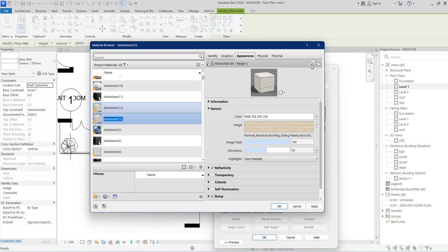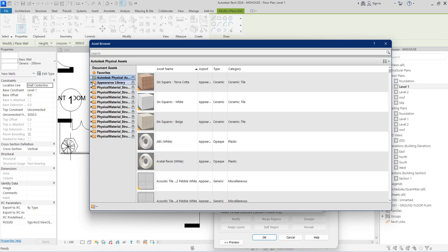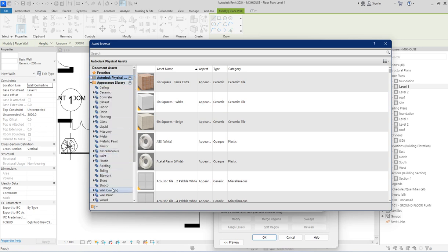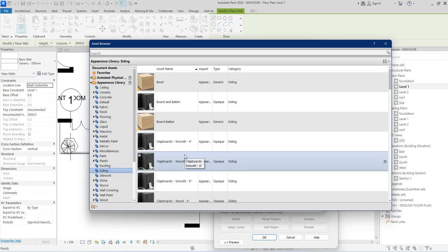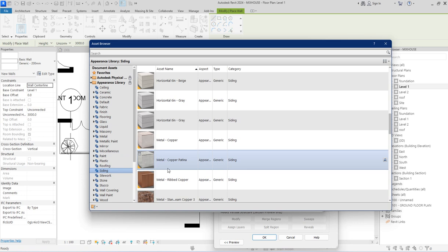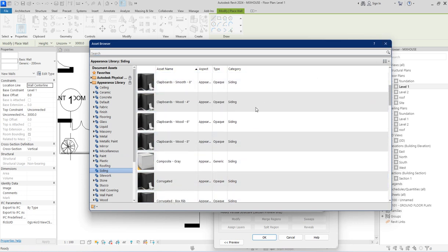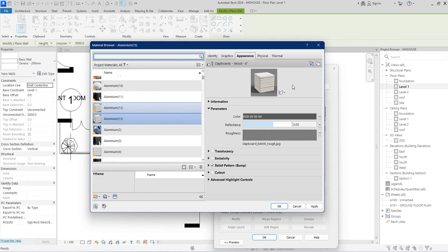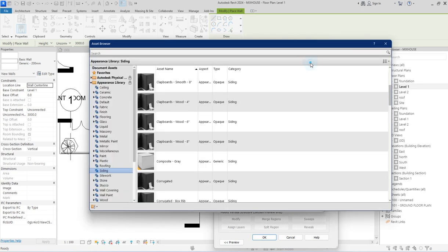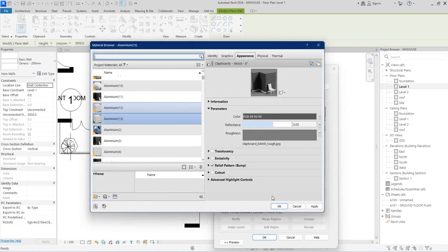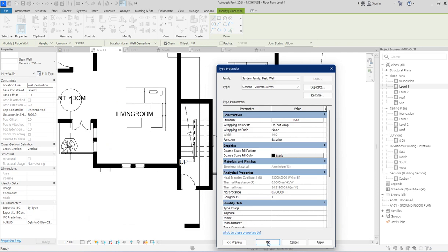After you duplicate it, you go to this and change it from the appearance as you have done. So go to siding, and instead of using the vertical or something like that, I'm going to use clapboard for this and give it some crazy value. I just want to change the pattern to which I'm doing. So let it update. Go to where I say it should go to now. Clapboard is okay, close down. Good. So it's updated and go there and say okay.